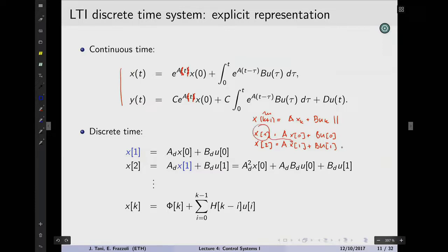I will get confused sometimes, because if you look in the textbooks when they give you the discrete time representation, nobody is going to be nice enough to remind you that you have to calculate the discrete time version of it. If you find an a in x of k plus 1 equals ax plus bu, they automatically assume that that's the discretized version of the a, if you have a continuous time system introduced before.